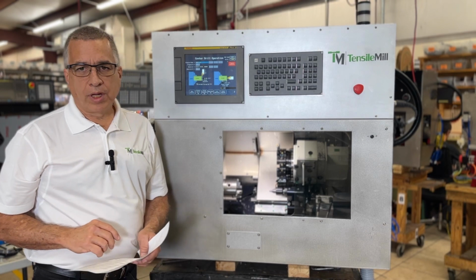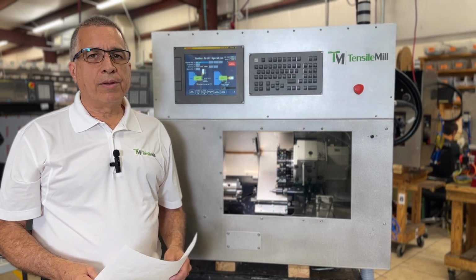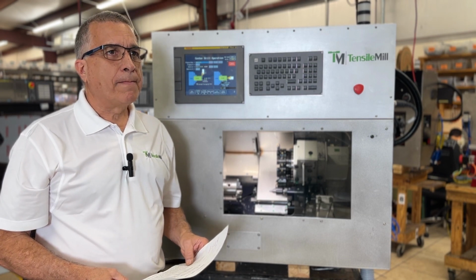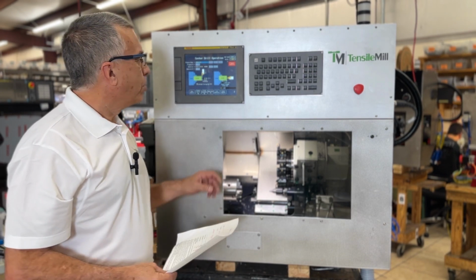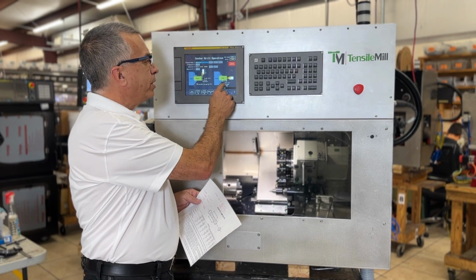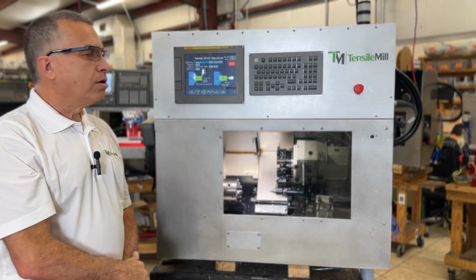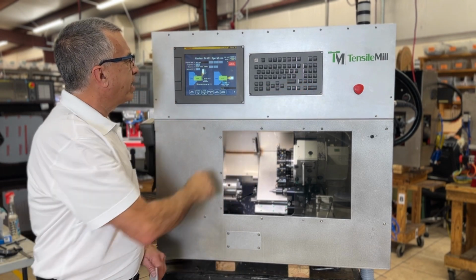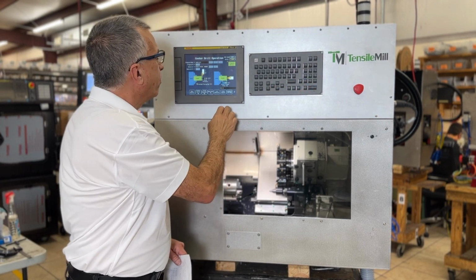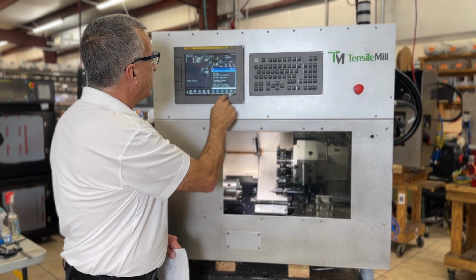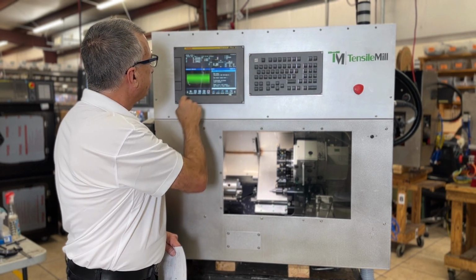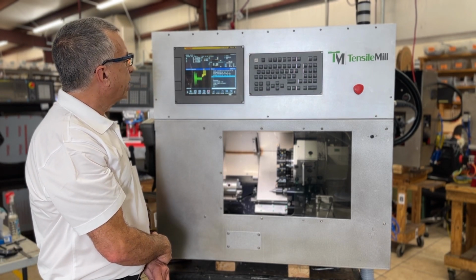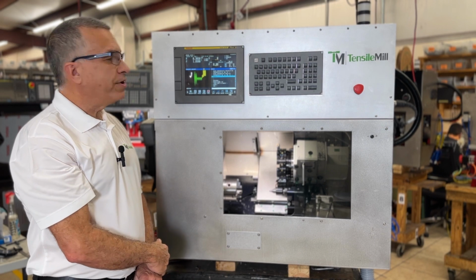And then the length it protrudes from the chuck. We're going to machine the part. I'm going to show you how to set it up on the machine. We're going to set the part 1 inch from the jaw. So specify there. We simulate the center drill. Same thing, facing first.